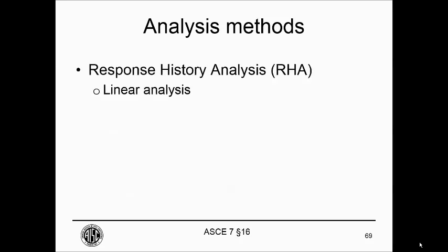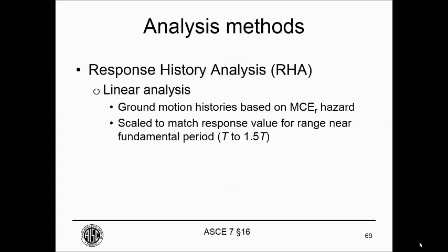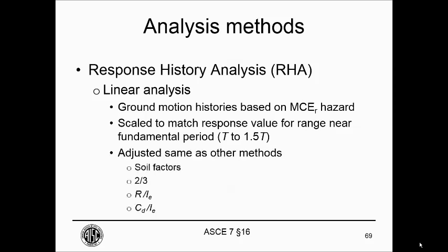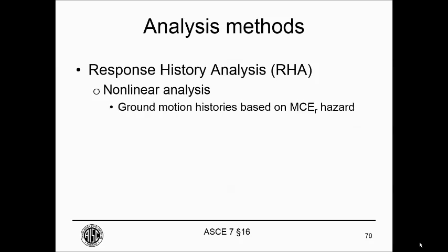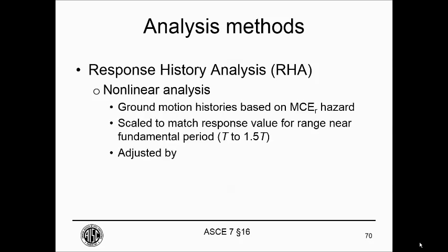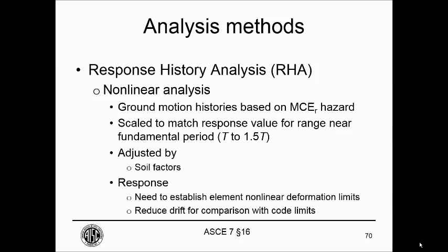Response history analysis can be done with linear analysis. You have to get those response histories. That's a bunch of ground motions. You have to scale them appropriately, and that includes, if you're using linear methods, reducing the required strength by R and so on. If you're doing nonlinear analysis, you need to get those ground motions and scale them appropriately and adjust them by soil factors, but you also need to set up your nonlinear model to represent how the building will behave. So you need to